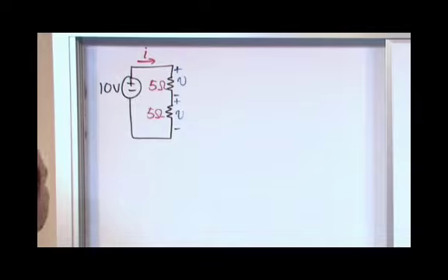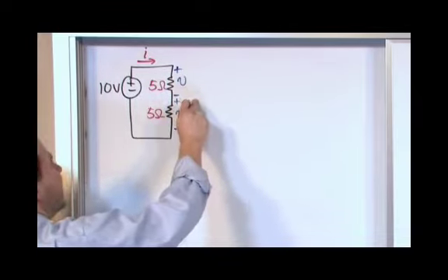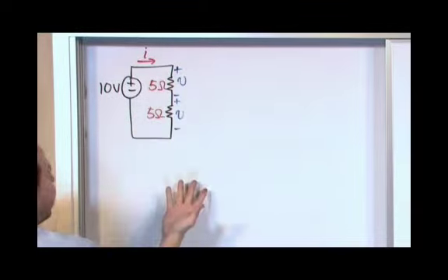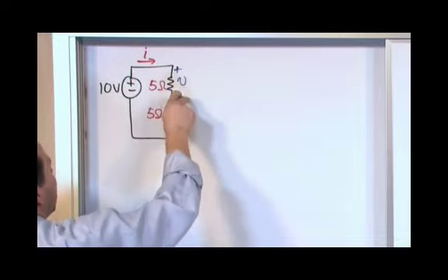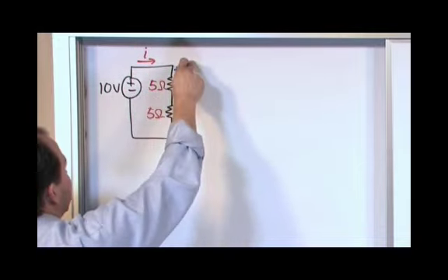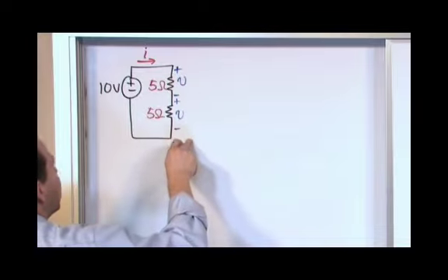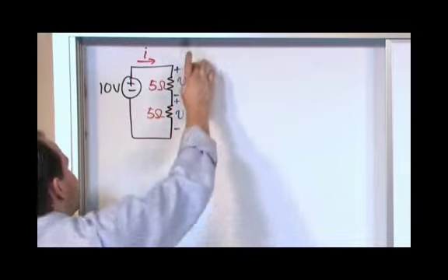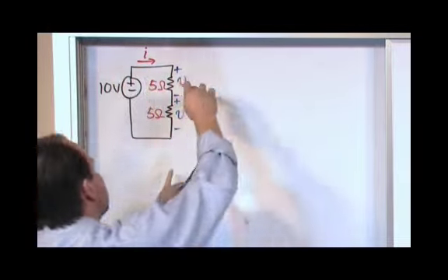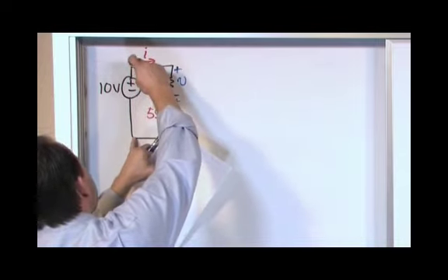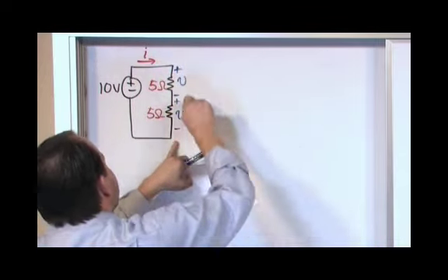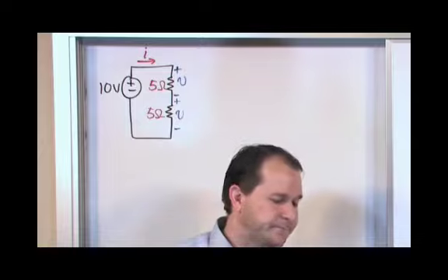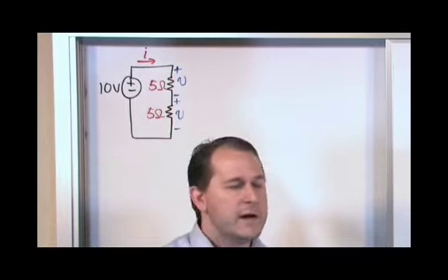And you know from Kirchhoff's laws before that this voltage drop plus this voltage drop must equal the 10 volts. Because if you do a Kirchhoff loop here, this is a simple circuit, you could do a loop, right? The way it would work is if you did a loop, it would be whatever voltage is here plus whatever voltage is here, minus this voltage up here because this is negative, has got to be equal to 0. So the sum of these voltages have to add up to the 10 volts. I mean, when you look at it, the thing is physically connected to the source. So the 10 volts is across the whole thing. So the voltage here and the voltage here, V1 and V2, if you want to call it that, they must sum up to 10 volts. Now, how do they do that?